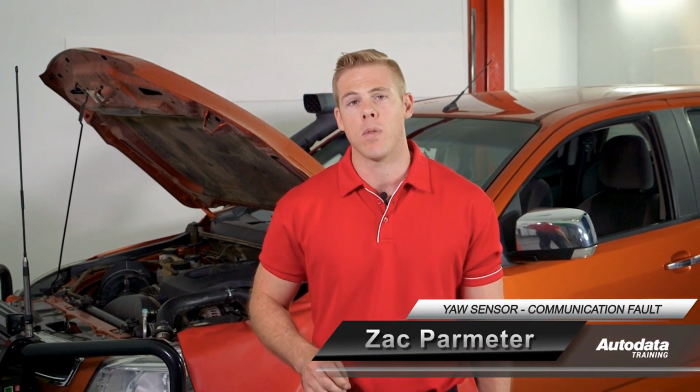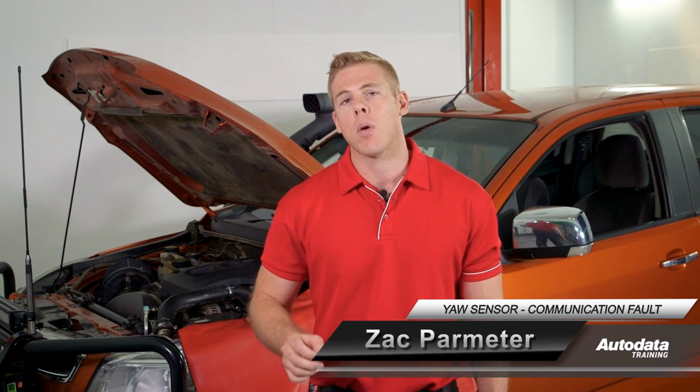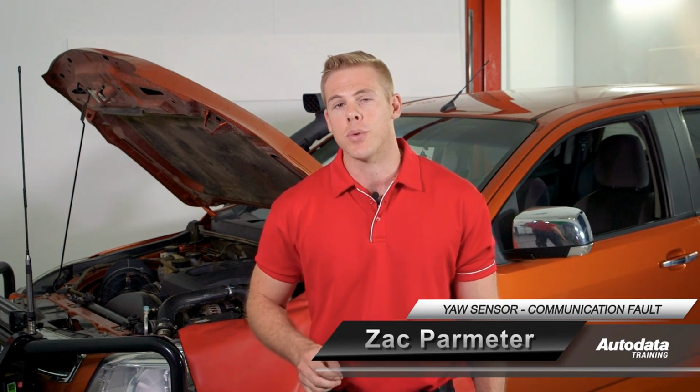is the key to a successfully operating electronic stability platform. If you lose serial data with the yaw rate sensor, it might prompt multiple codes to set in multiple modules. So, let's look at the best way to address these U-type codes.